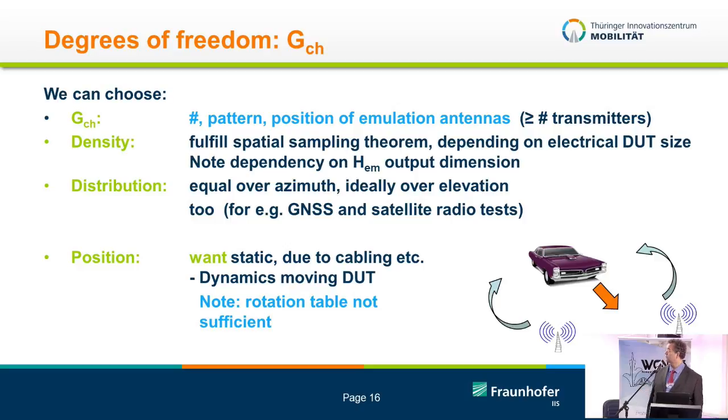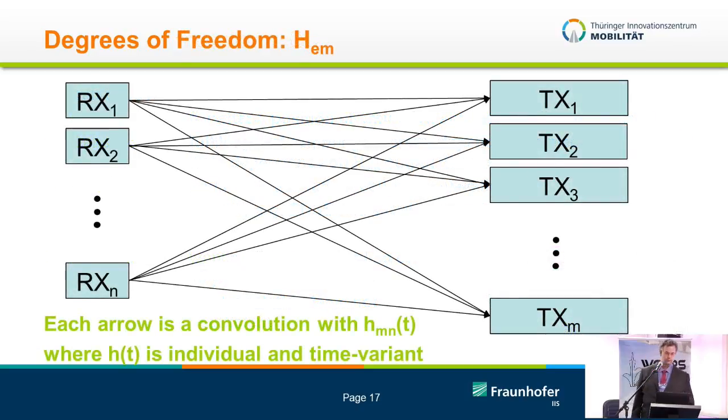if you need a 3D channel representation for whatever reason. And now we come to the most interesting thing, and that is the channel emulator. The channel emulator is easily the most expensive part of your setup. And that is because you have a set of inputs, you have a set of outputs. You can first discuss the RF parameters that are required. You want to have them in a wideband coverage because you do not know which frequency you're going to measure. You want them with sufficient dynamic range that you can make your measurements, including the channel.